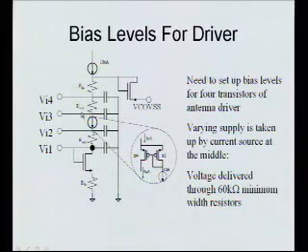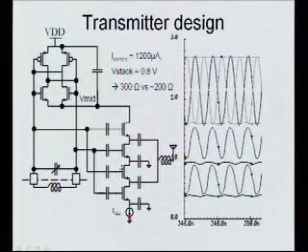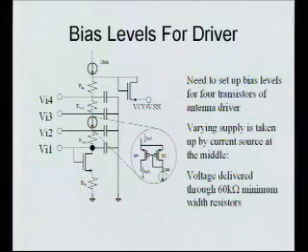And there's no particular obvious reason why this is the best way to do it, but just fiddling around with simulations, I found that I had the best sort of consistent performance if I let my supply variation appear between these nodes rather than across one of these individual drivers. Just kind of a heuristic thing. But I like this trick, that's why I put it in.